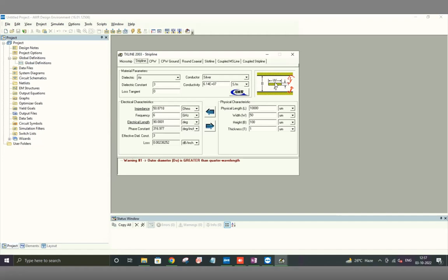So that means just changing the center pin increases inductance. So reducing the center pin width increases inductance, decreases capacitance, which means Z naught will go up. Usually, the gap, the B, is fixed in a structure, so you only control the width of the central trace. That's the only thing. So if you want higher impedance, you have to make it smaller width. If you want smaller impedance, you have to make it larger width.